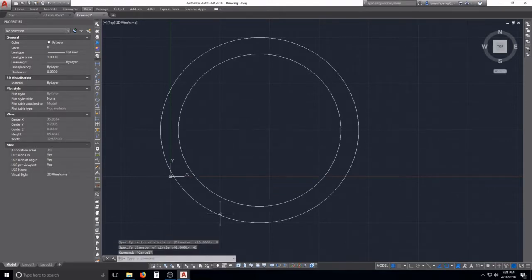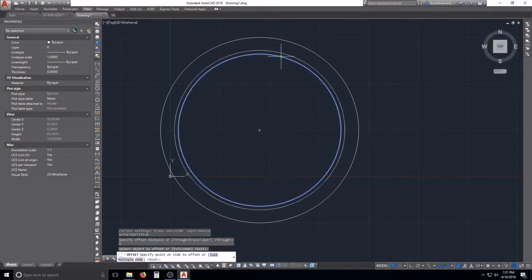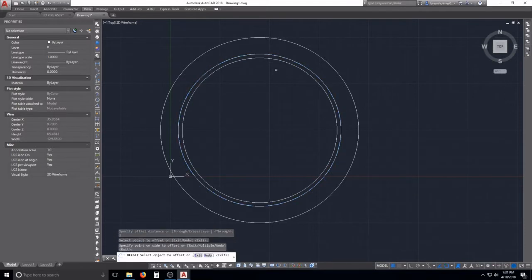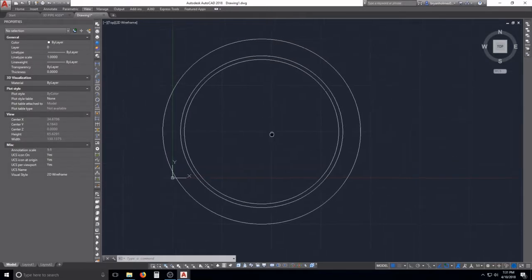There you go. Now the wall thickness here, I could care less, so we're just going to offset that, say half an inch, or say 1 inch. Offset, O for offset, and then just type in your distance, and that's say 1 inch. So it's going to offset 1 inch either side, whichever way. If I do it this way or that way, whichever way I'm on the line. So we're going to do an inside. There you go, guys. That is the bulk of what we're doing.